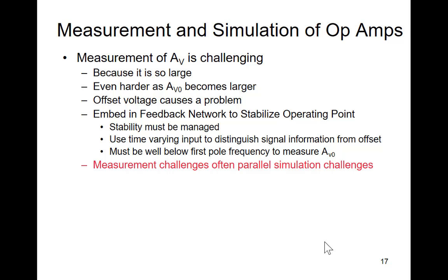You think, well, I got a really high gain op amp. I'm going to use an audio frequency range. Where are you using it? If you use it in audio frequency range, you're using it out here. What gain do you have left where you're using it? This might be the audio frequency range you're interested in right here, right? That op amp doesn't have anywhere near an infinite gain anymore. That gain might only be 100 or 1,000, or if you're at the upper end of the audio range, it might be well less than 100. So your assumption that it's an ideal op amp starts to fall off quite a bit, doesn't it?